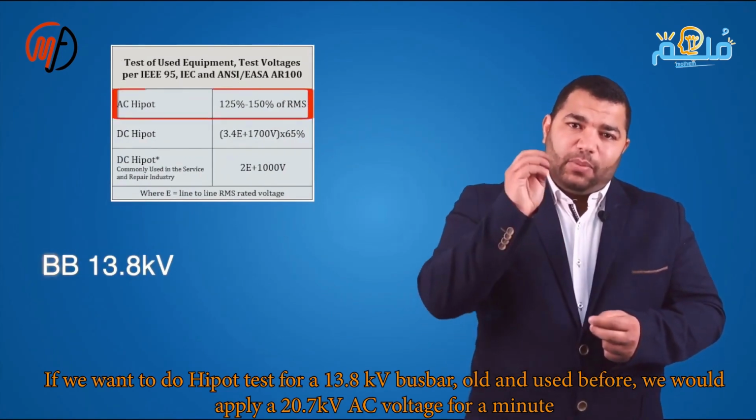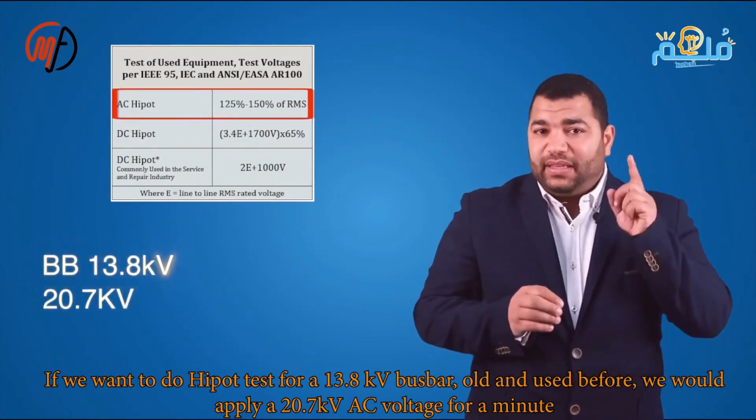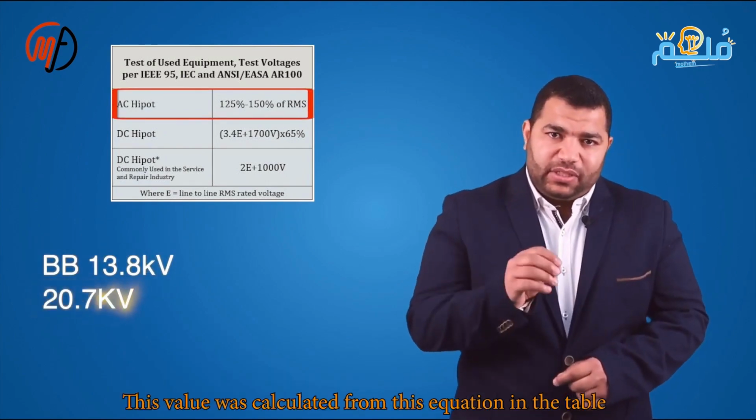However, using DC in a hypot test is not recommended because it creates a constant electric field, leading to treeing or water treeing, which may cause insulation breakdown.